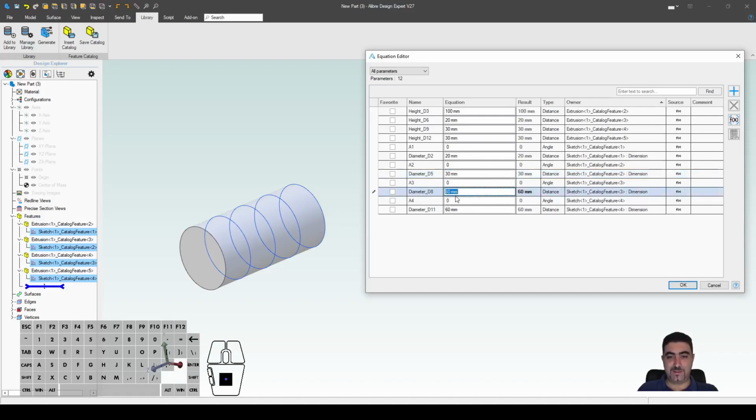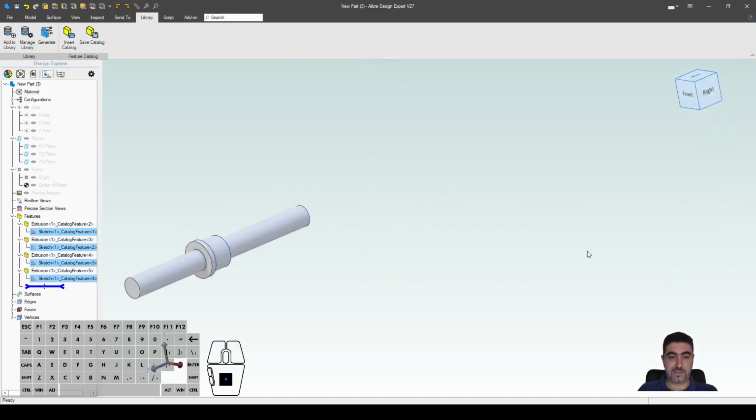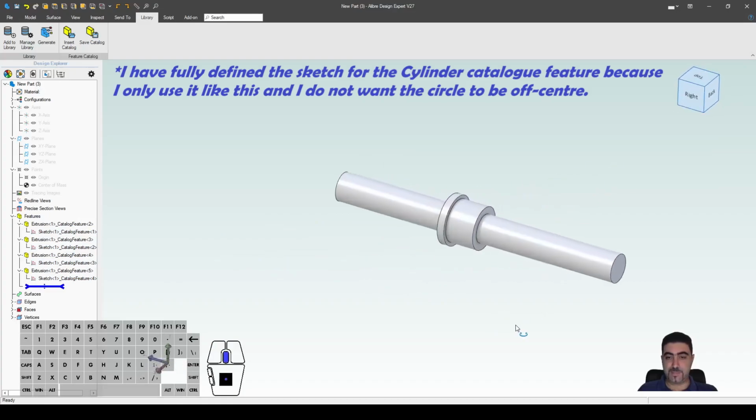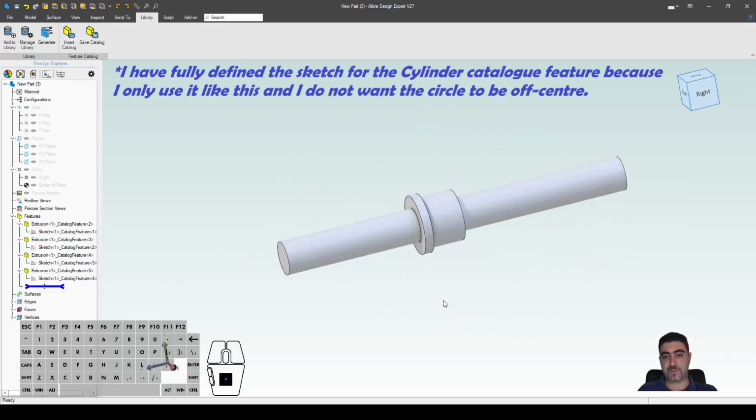And then we need a stop for that bearing. So this is going to be 35, I'm guessing. And this doesn't need to be very long. It just needs to be 5 millimeters. And then we have an output part to that shaft, which might be again 20 millimeters and have another 80 millimeters of length. And if I hit OK, look, I just made this shaft, right?